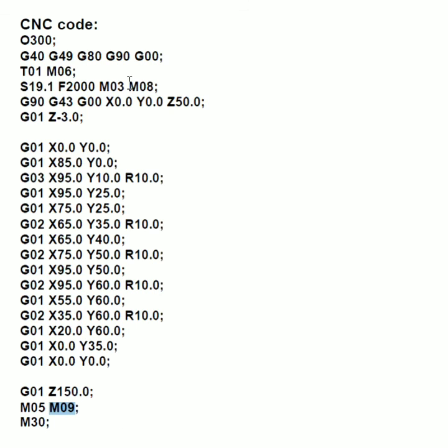In the definition statement, we turned on the coolant by using code M08. And lastly, in the closing statement is M30. M30 is to end the program.